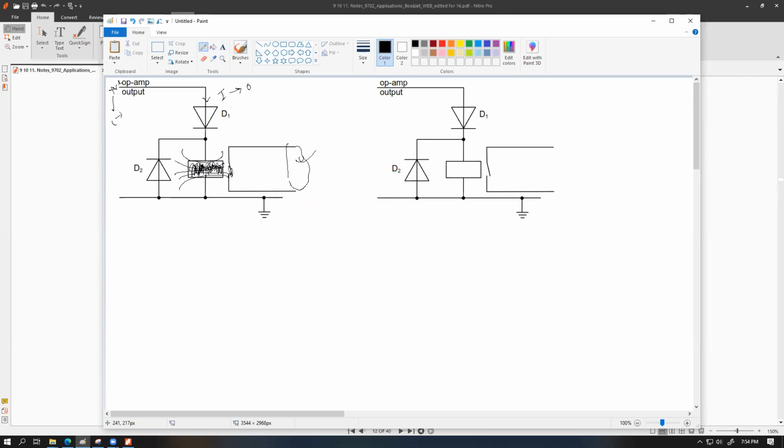Now, by Lenz's law, whenever electromagnetic induction happens, it will always try to oppose the cause of the electromagnetic induction. Because this is a solenoid, as the coil starts to lose its magnetism, it will try to maintain that original magnetic state and create its own current flow so that the coil would not lose its magnetization. This is not exactly identical to, but quite similar to what we have seen in electromagnetic induction.